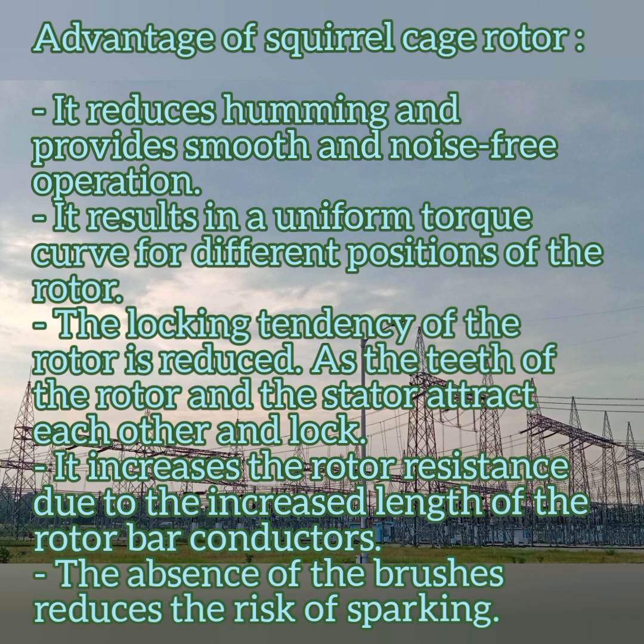Then the locking tendency of the rotor is reduced, as otherwise the teeth of the rotor and the stator attract each other and lock together. It increases the rotor resistance due to the increased length of the rotor conductors. Then there is an absence of brushes, so automatically it reduces the risk of sparking in the rotor.